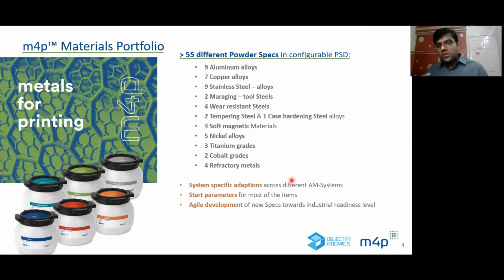This is required when you think of being a powder particle and how you will respond when you are in a machine. Many things change in a different machine. For example, you are normally sitting nicely in a bed, lifted up with the platform, and your only job is to spread on the build platform. But in a different machine environment, say a Renishaw system, you are placed in a hopper and you want to go down. So your first job as a powder particle is to go down, and your second job is to spread to the build platform.